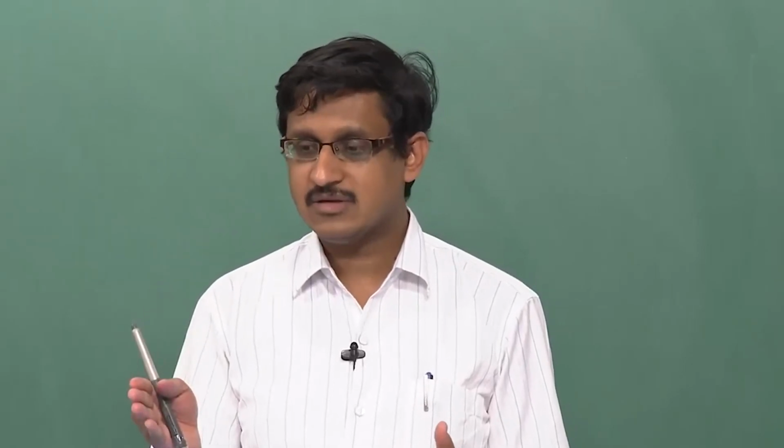So there will be some resistance less than Z0 which is pulling the voltage down and then it is increasing to V0, okay. What I wanted to say is that initially you have a capacitance, okay, but the capacitance is not the alone discontinuity that you have. In series with the capacitance there must be an inductor so that a fraction of the voltage is actually developed, reflected back and then gets added to it.